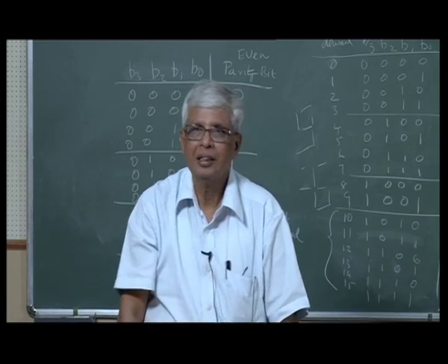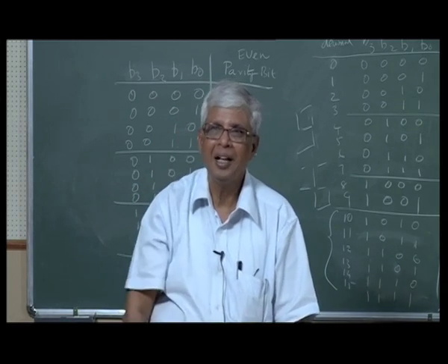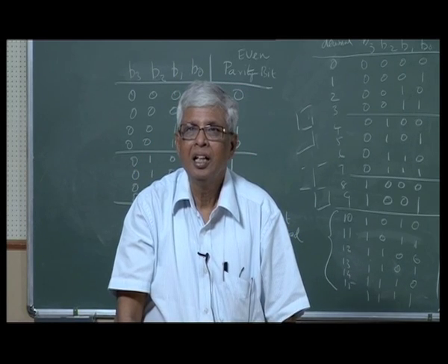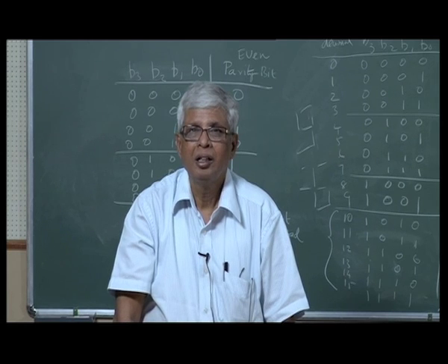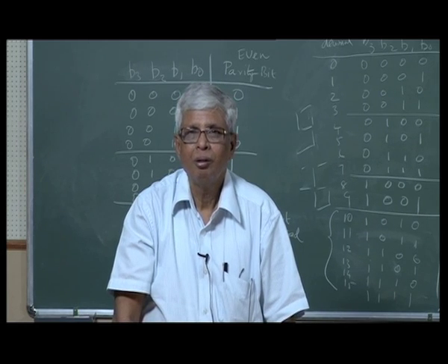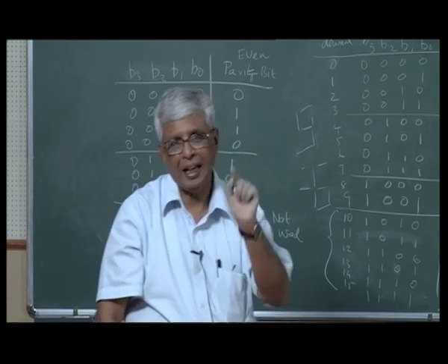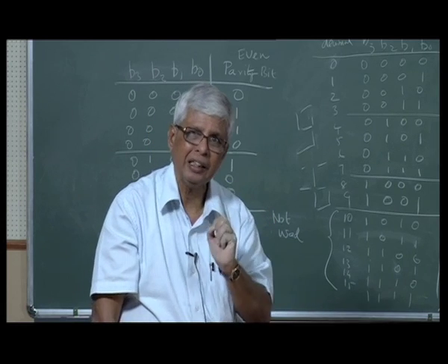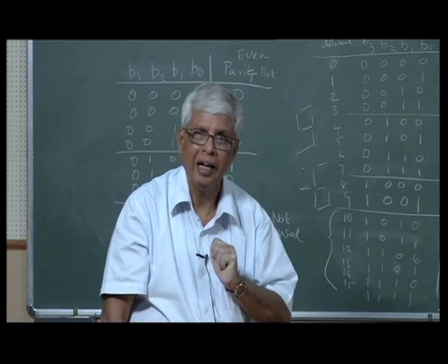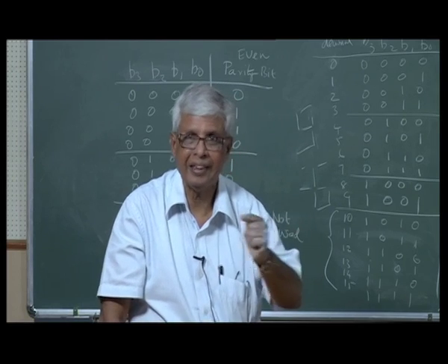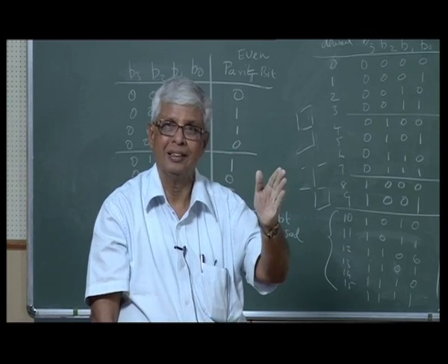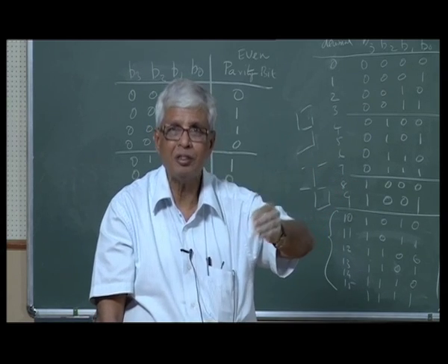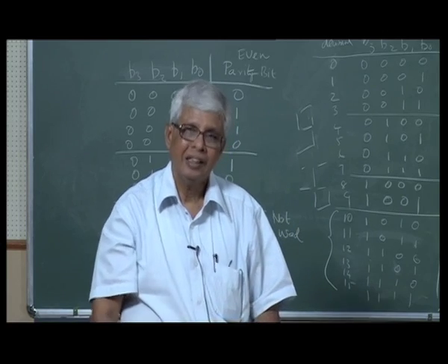Yes, sir. Calcutta man. You are Calcutta, right? Say it again. Okay, tell. What is your question? Sir, I was asking what is the use of keeping high impedance? 0 output and no output mean the same thing. I have a gate. I need to connect it to my circuit. Every time I cannot disconnect, connect, solder, desolder, cut it, add it. It remains connected, but I don't want to recognize it. As if it is not there. It's an attachment which doesn't exist. That is why I need it.